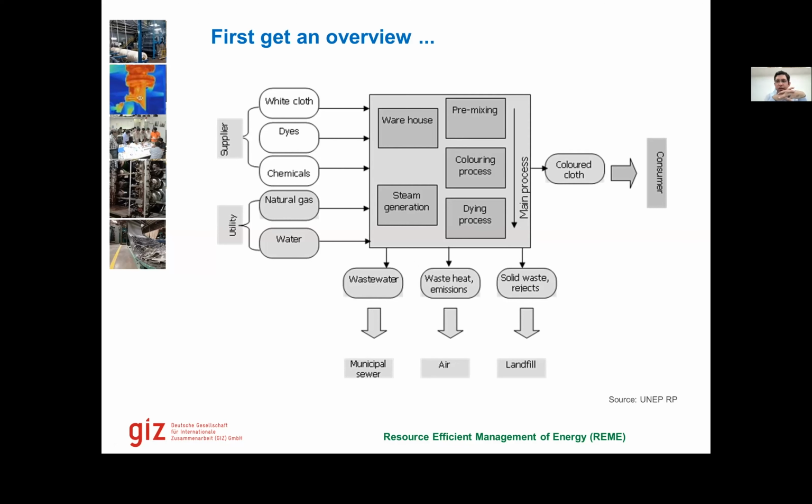So if we are doing it for energy, for example, I would say we take the whole box of one company. On the left hand side, we show which are different types of energy coming in. For example, electricity from grid, coal for steam, coal for space heating or process heating, natural gas for singeing process, for example. Or if we are purchasing steam from somewhere, we can also show purchased steam or purchased chilled water. On the right hand side, we can show our main product output. If it is a denim fabric company, for example, we can say that it was denim fabric, finished fabric going out.